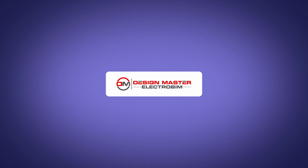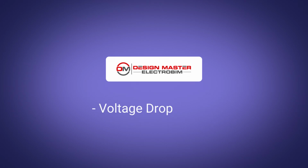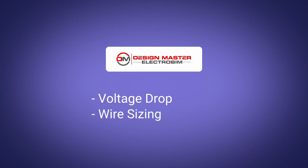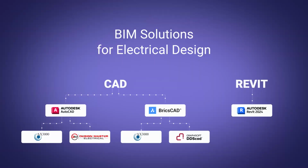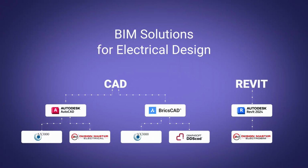That's where something like electrobim comes into play. It's an add-in for Revit. It adds voltage drop that works correctly. It adds wire sizing. It adds fault calculations and single line diagrams. If you want Revit to deliver on the promise of BIM for an electrical engineer, you are going to need electrobim on top of it.